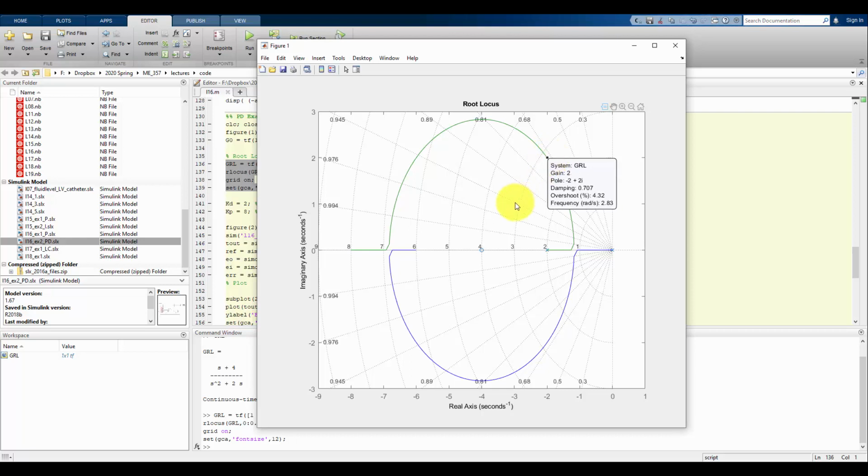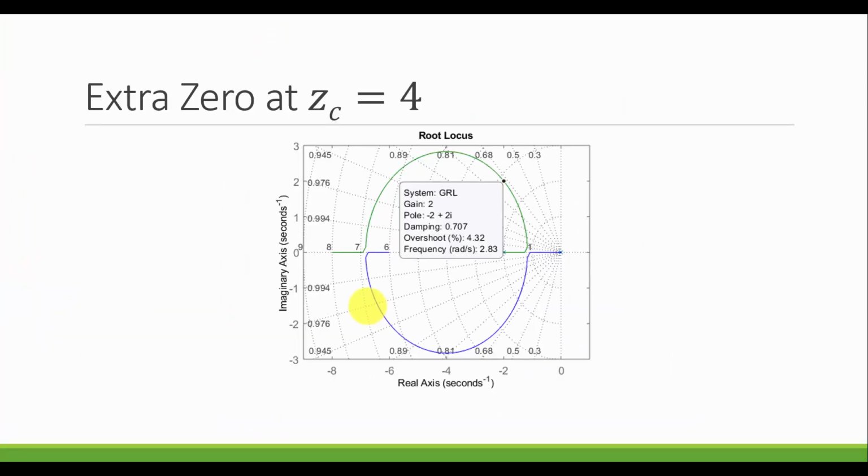All right, so right there, we see that the pole on our root locus is -2 plus or minus 2j. Remember, I really only have to click one since they're automatically going to come in complex conjugate pairs. I will show both here just for the sake of it. But if we select one, we've automatically selected the other one. All right, so either one, we see that it tells us to use a gain of 2. So if our k value is 2, then the poles of our closed loop system will be at -2 plus or minus 2j. So I'll recreate here on the slide, and now we can put it together.